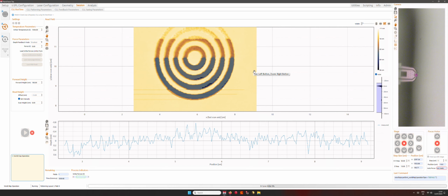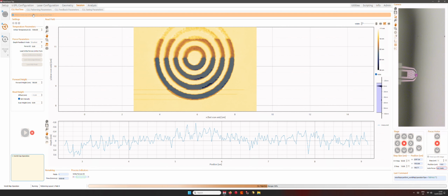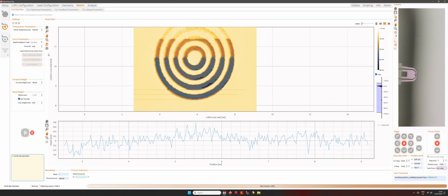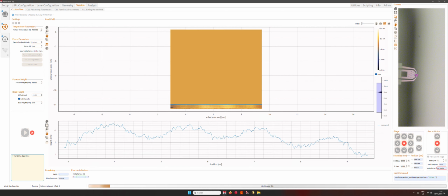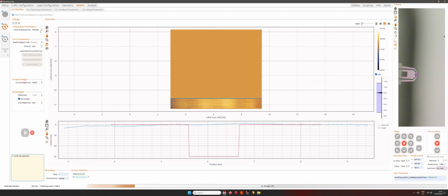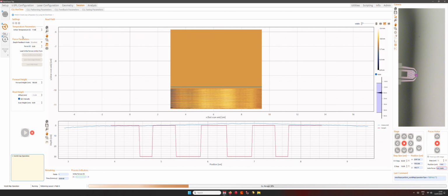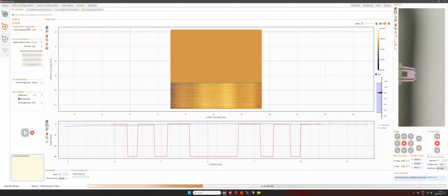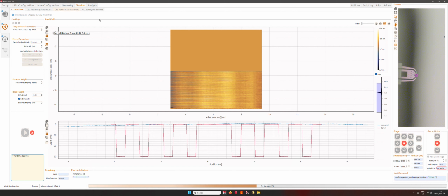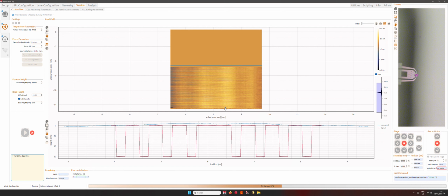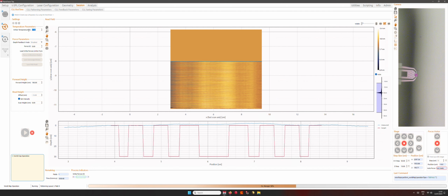As the temperature can still be changed when we write our field, we can also see how the temperature affects our patterning and our thermal bending. In general, as you can imagine, as we increase the temperature, we also increase the thermal bending effect. So now it's probably too low. I will increase it to 1100. I'm not able to write, so maybe I put 1150. Just too low.